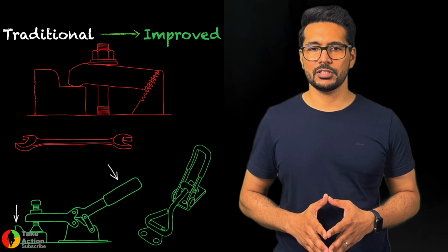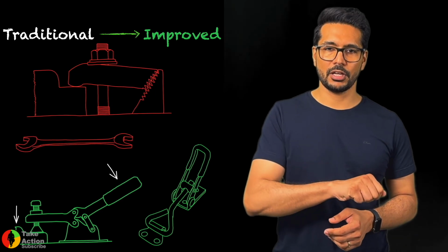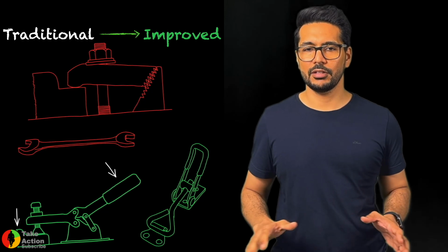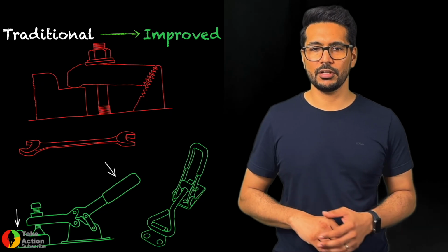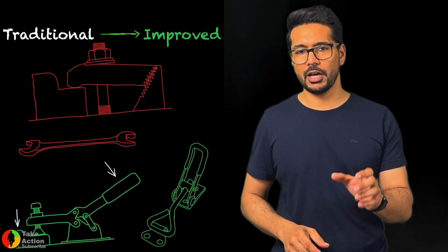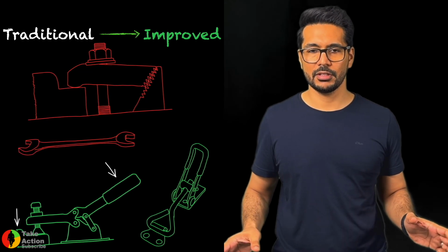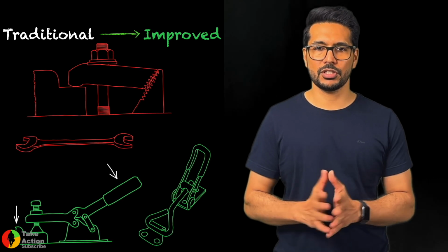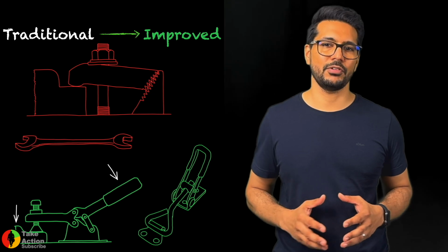They can be just simply clamped with hand and can be very easily opened, and that eliminates the whole work of loosening, removing the packing plates and replacing the packing plates as per the height of the parts. Everything is eliminated if we have these state-of-the-art clamps which are very easily available in the market.